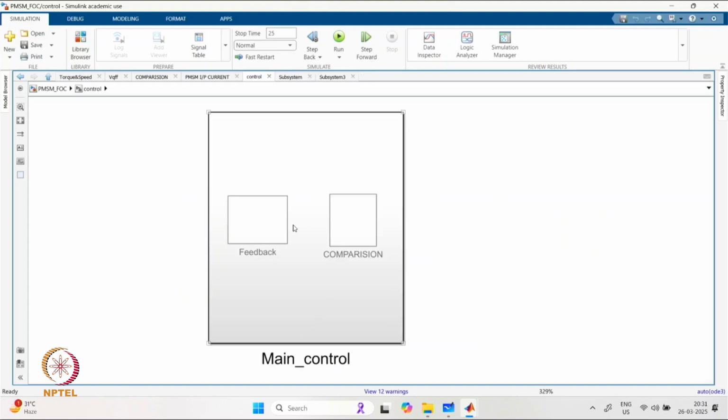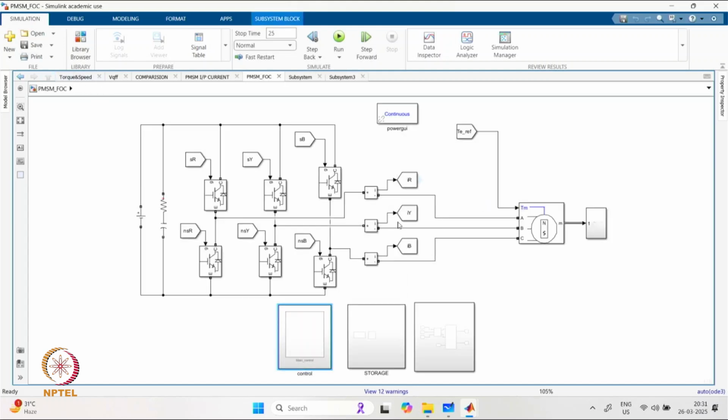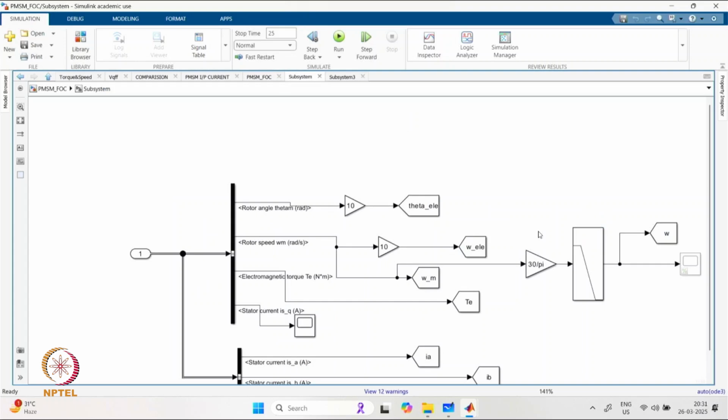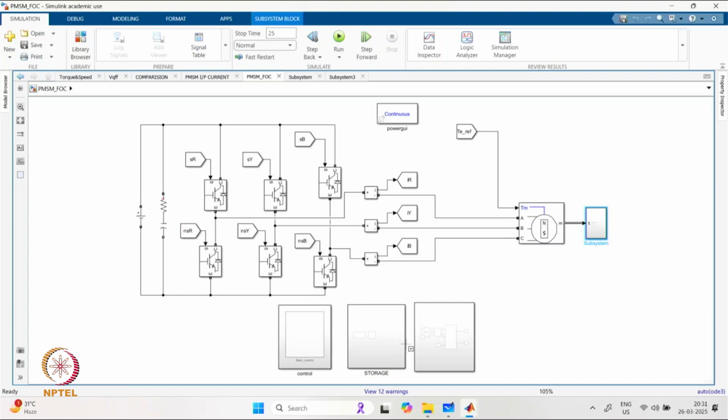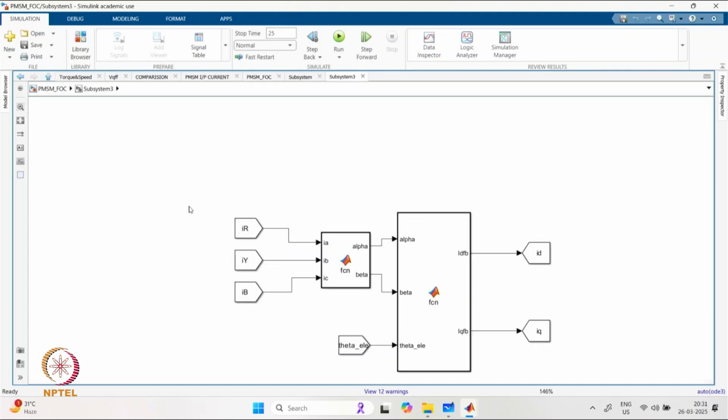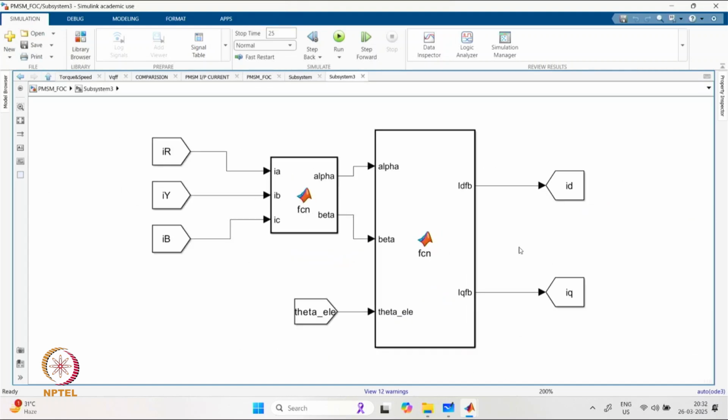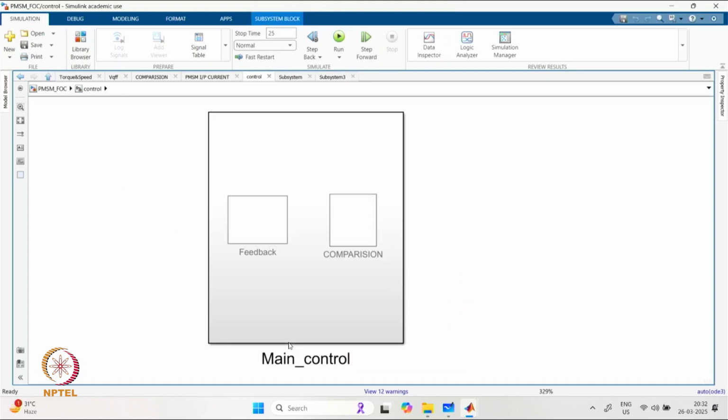We have rotor flux oriented vector control to be implemented. For that we need measurements of the line current, and we need certain feedback taken from the speed encoder and position encoder over here. So we are taking omega and then the position of the rotor as well. These are the feedbacks generally expected to be available on the system, and these values are transformed to the DQ frame of reference as and when needed.